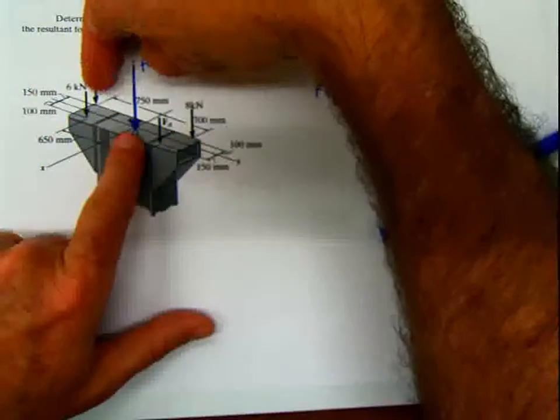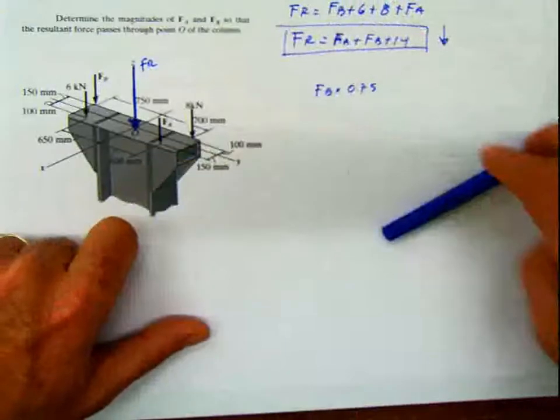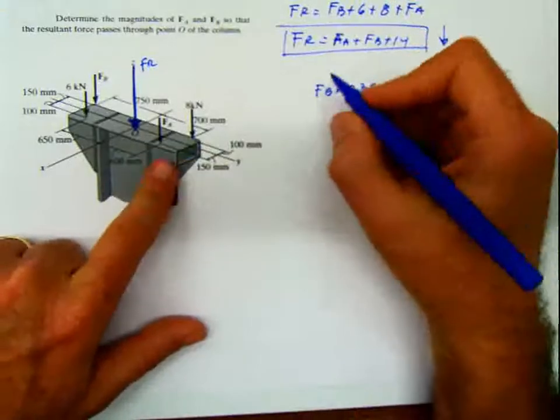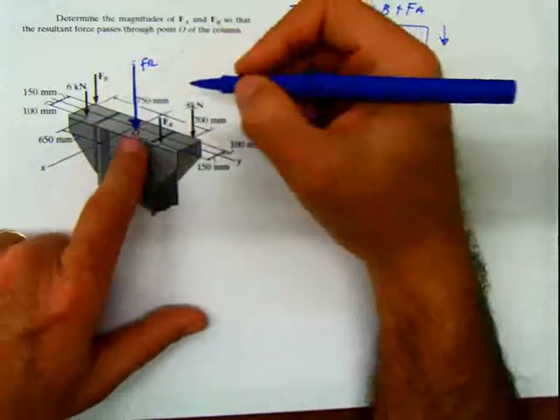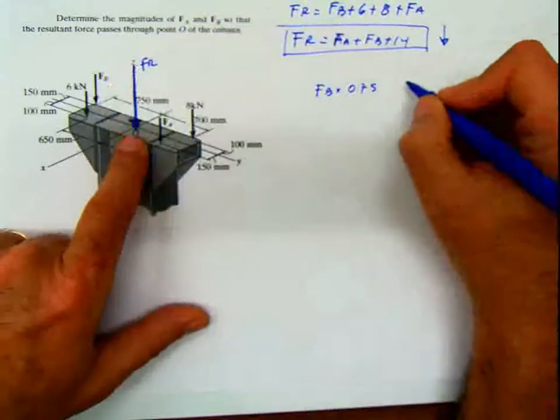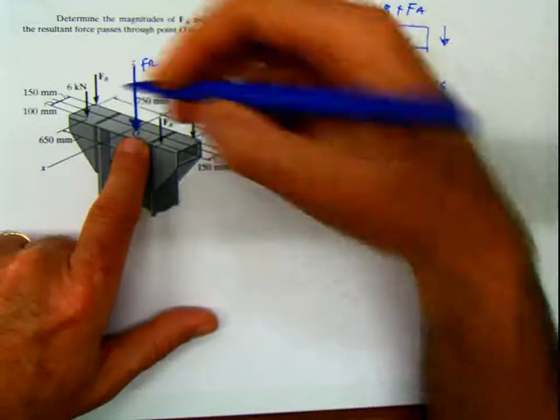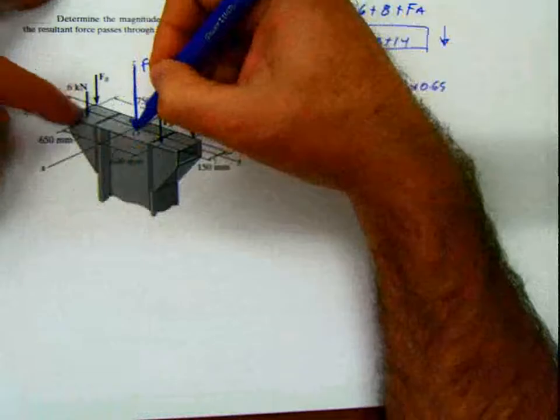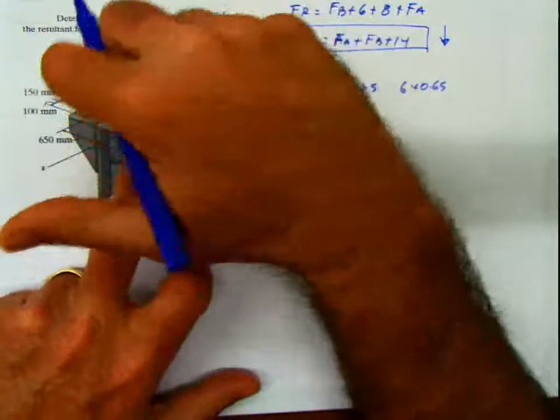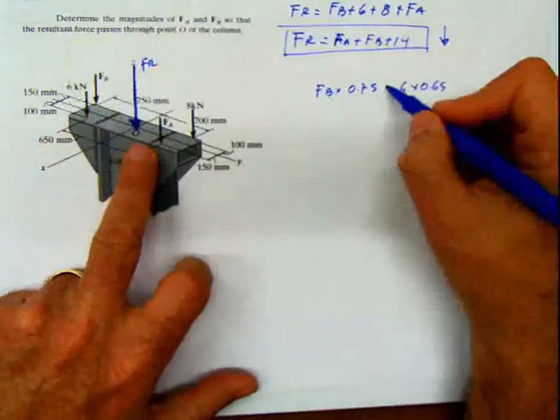Just see it, apply the force here, and that's going to try to rotate in that way. So that means that it's going to be positive, because it's going to the positive direction of the axis. This 6 times this distance of 0.65, same story. Because if I am here and apply the force here, that's going to produce a rotational movement with the x-axis.